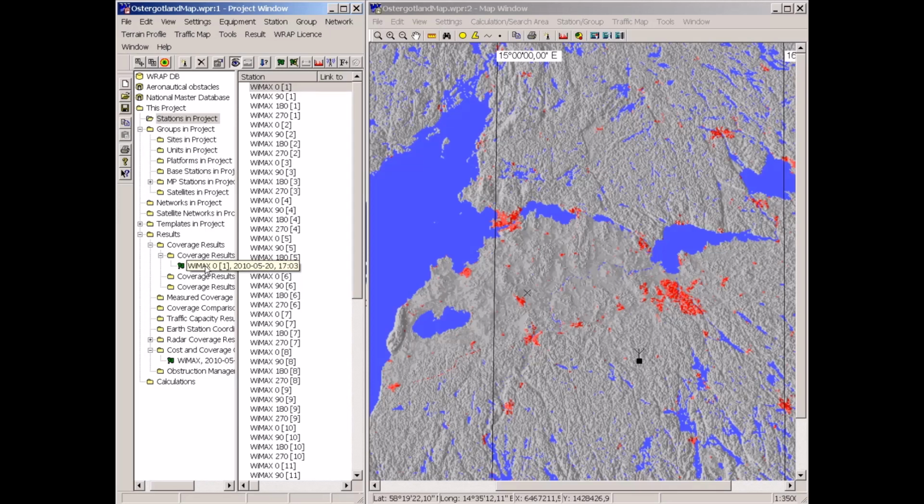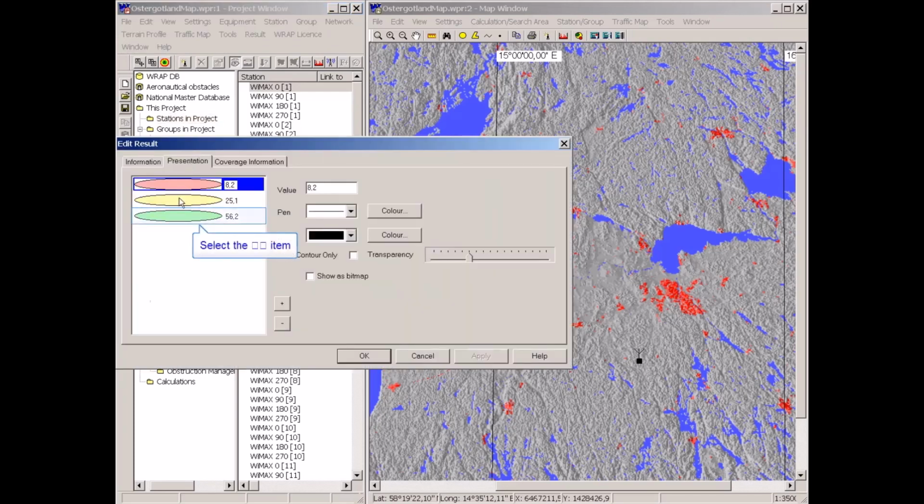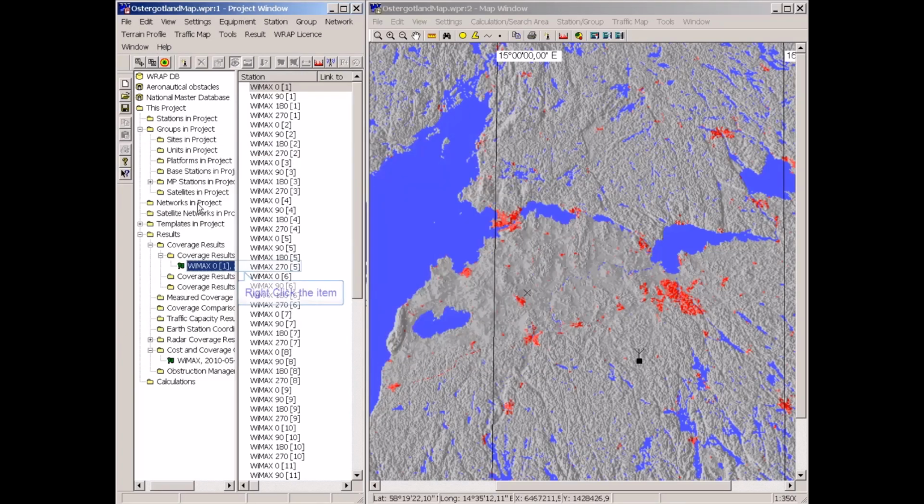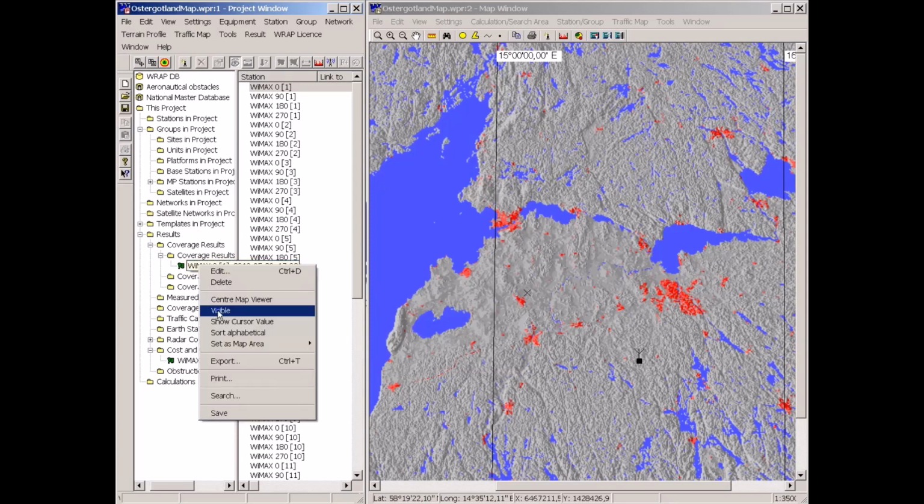So, here it shows that within the 30-kilometer radius that I calculated, if we wish to have line of sight coverage to every point within that circle, we have to use a 152-meter high antenna, which of course is not realistic. So let's put in a few antennas here. What can we do with 5-meter, 15-meter, 25-meter high antennas?